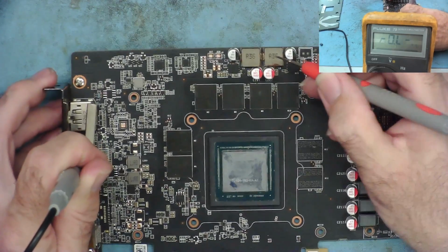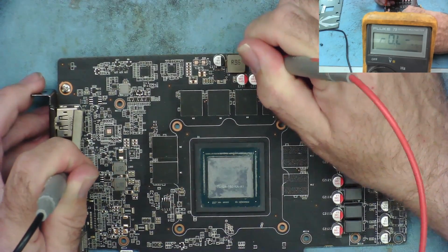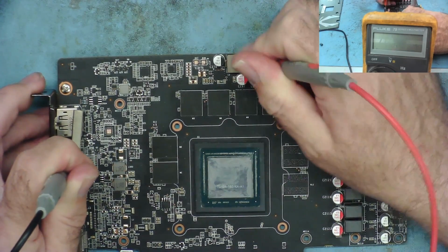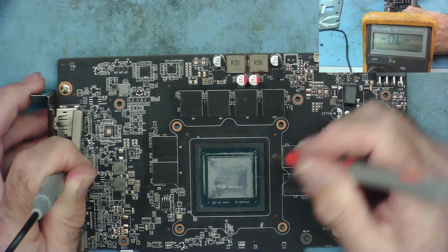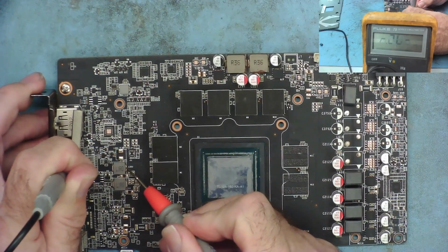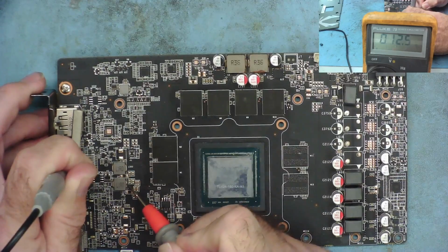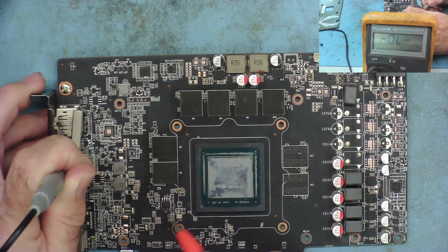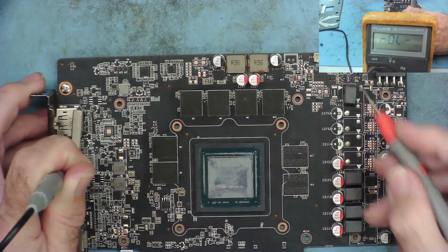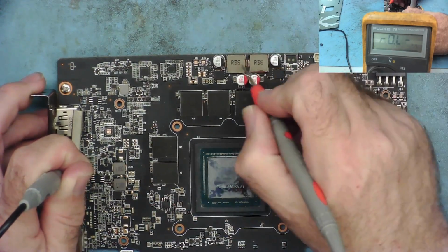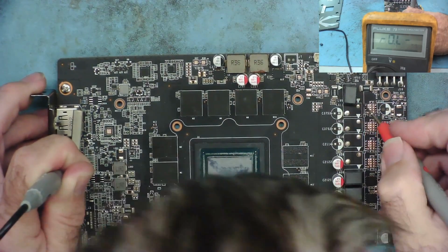So there are two rather large buck regulators here, which are probably going to be the RAM phase, as I'm not familiar with these cards at all. Yeah, like 70 ohms, and that looks normal for a RAM phase. There's two here. That one was reading 3.8k. Right, this one at 12.5 is probably the PEX rail, the PCI Express, or it's the voltage for the memory controller. But there's another one up here which might be the memory controller. What was this one reading again? Well, that looks like RAM, 69.